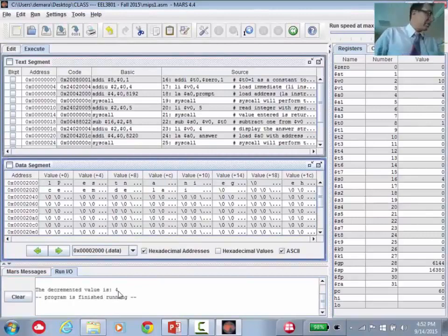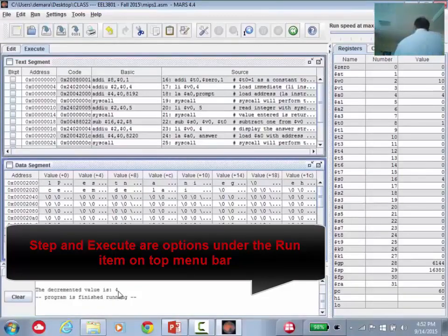You're going to say, well, it happened too fast. I can't see what it's doing. That's the single step mode. You can go to step mode and look at this instruction by instruction, and you actually see these registers change. Some of these changed. If we look in the program, the final value was contained in A0 because that's the register that outputs it. If we look at the code, we'll step through, we'll show you a step. But look at the code.